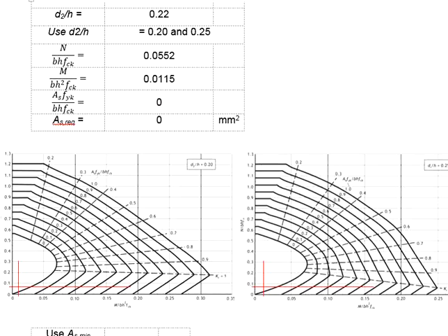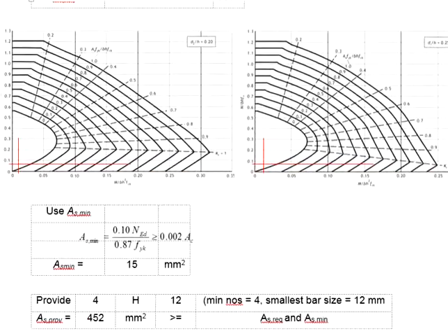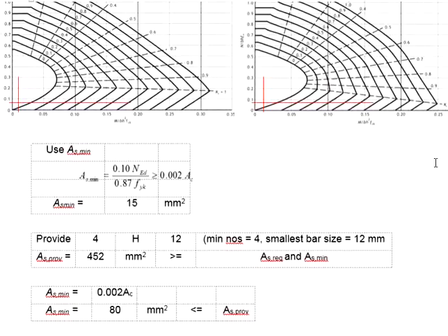But you know that definitely you cannot put pure concrete without any reinforcement. Now you do the checking for the As min. The As min gives you 15 mm square only. Theoretically, the As min will determine the amount of reinforcement bar provided. As long as you provide the rebar area more than this, it is theoretically adequate. However, there are other considerations.